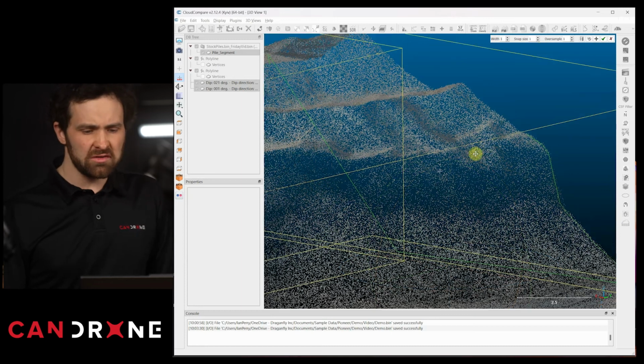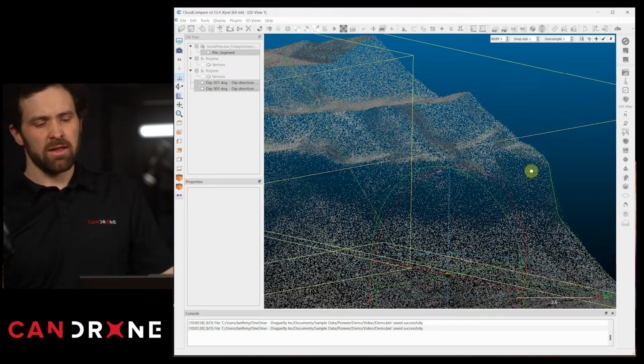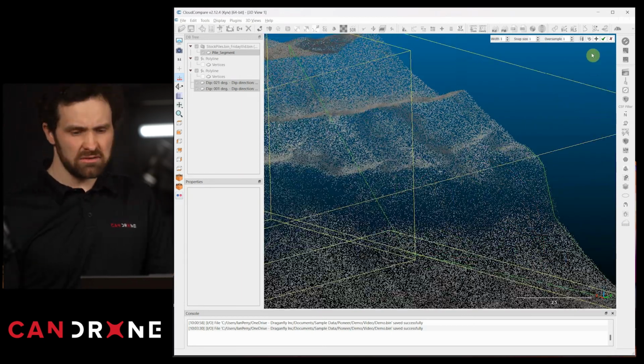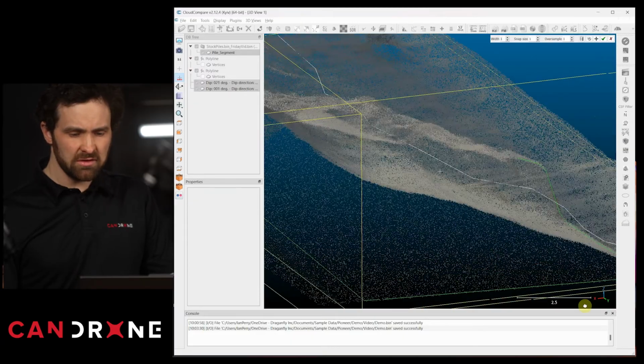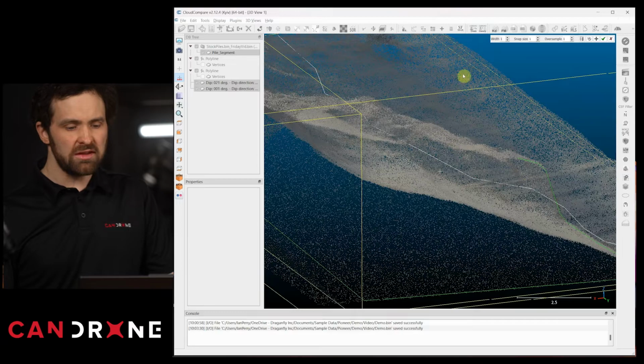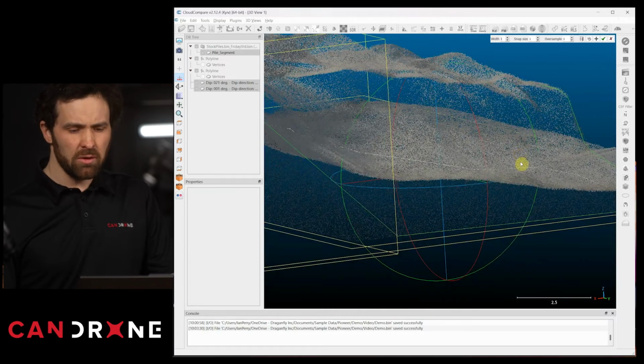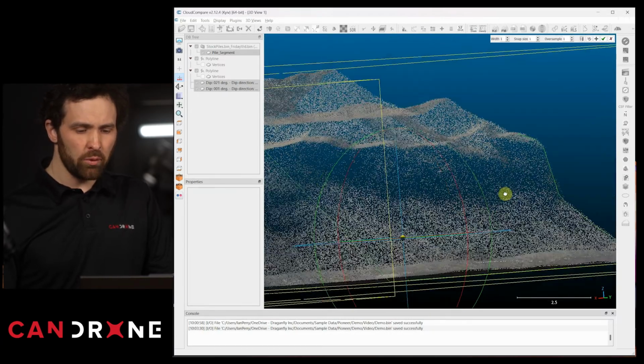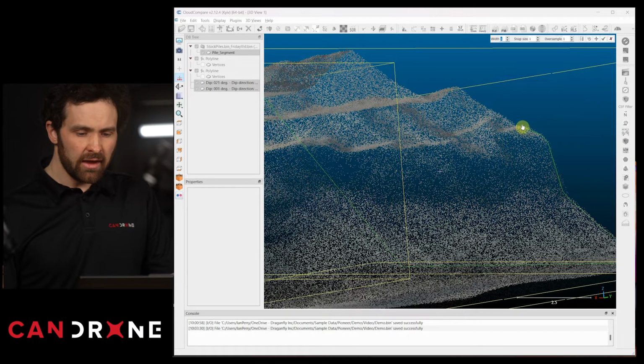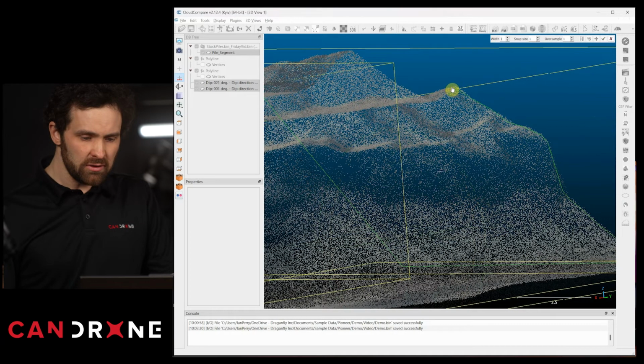The easiest way to do this is to click on the points against the horizon. If I click like this, it's way too easy to grab points that are in the scene further on down. So pivot until you're actually looking at points against the skyline and continue on your way, tracking the topography of the point cloud from the side.